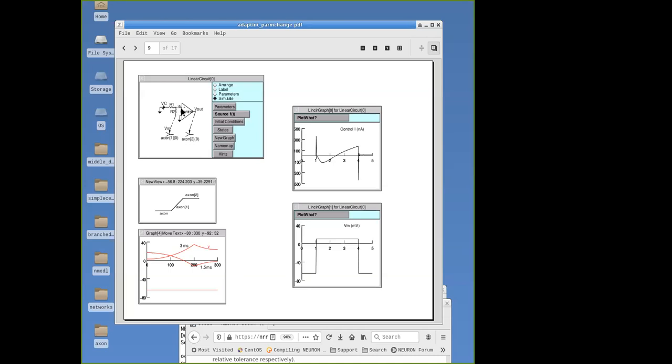So we're looking at essentially the difference between these potentials. And we're amplifying it and inverting it and forcing that back into the cell as a current. Okay, so the gain of this inverting operational amplifier is what's closing our loop. We have a negative feedback circuit. All right, so we're trying to control the potential at that point, and we see that we have controlled it very nicely. Membrane potential jumps up, stays a while at that new potential, 10 millivolts, and then jumps back down. Beautiful. The clamp current looks kind of plausible.